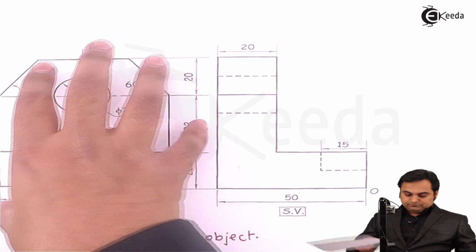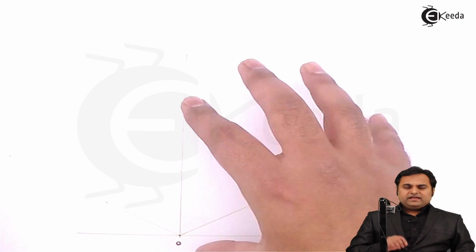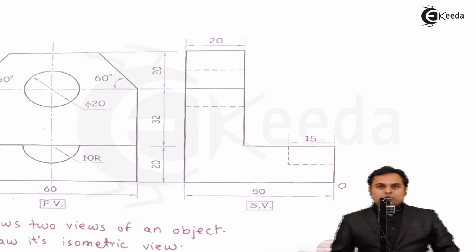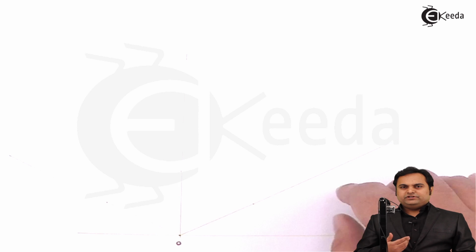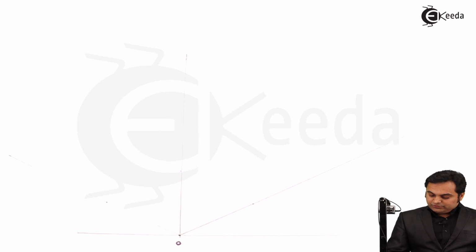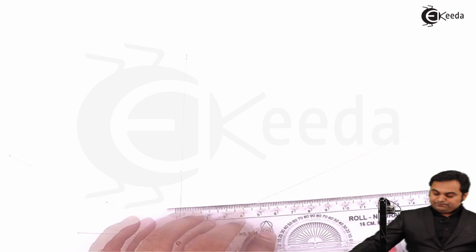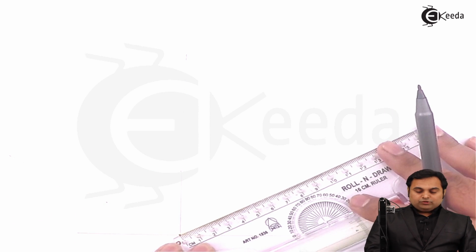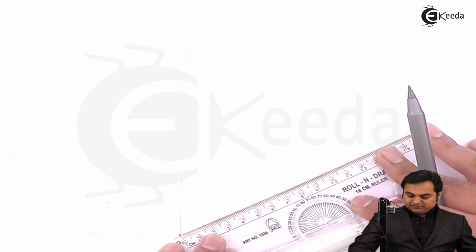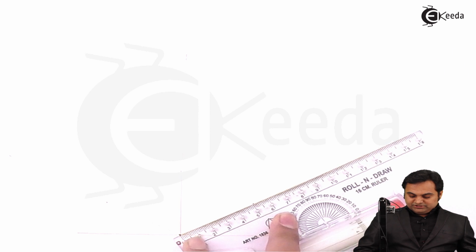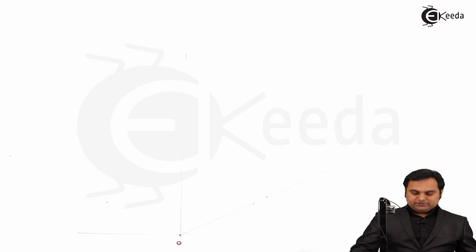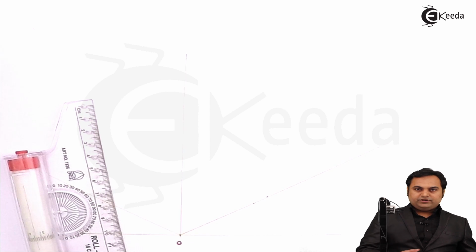Next, in the problem, they have given the origin in the front view, as I can see here, and even in the side view. Origin is that point which is close to the observer, or we can say the reference point. So in this diagram, here will be the origin. This is the origin for us. And now, when the object is kept on the origin, like if I lift it from the front view, and when I'm keeping the front view on this side, then origin is here and length should be along this line. So the length of the object will be marked here, height on this side and width over here.